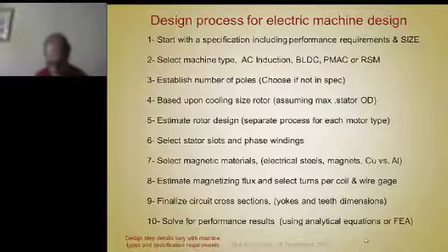And the reason that is possible is because when you double the number of poles, the thickness of the yokes are cut in half. So there's several things you can do with that extra radial space. You can make the machine smaller, saving weight, mass, and inertia, or you can increase the torque density by increasing the torque itself, by keeping the OD of the machine the same and making the rotor larger in diameter by keeping the stator slots the same depth. You make the rotor larger in diameter by the amount you reduce the yoke thicknesses too.